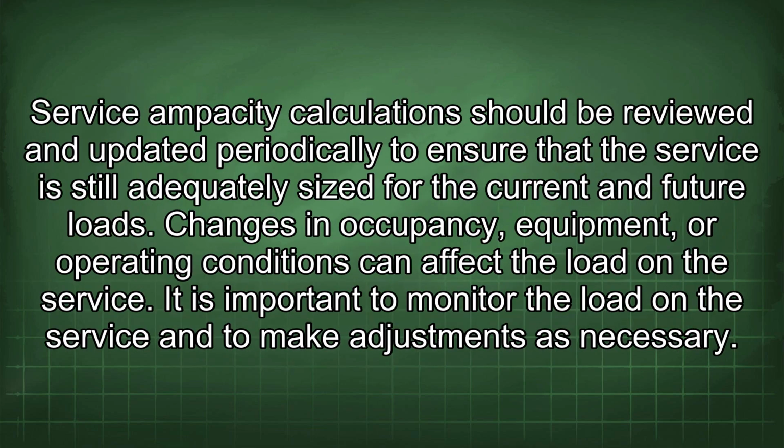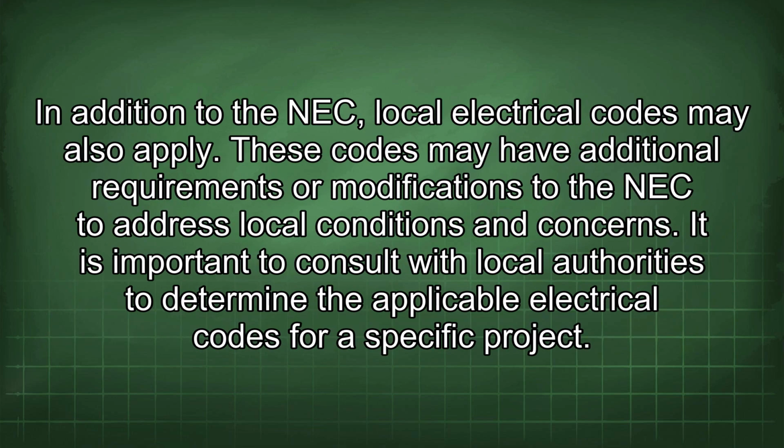Service ampacity calculations should be reviewed and updated periodically to ensure that the service is still adequately sized for the current and future loads. Changes in occupancy, equipment, or operating conditions can affect the load on the service. It is important to monitor the load and the service and to make adjustments as necessary. In addition to the NEC, local electrical codes may also apply. These codes may have additional requirements or modifications to the NEC to address local conditions and concerns. It is important to consult with local authorities to determine the applicable electrical codes for a specific project.